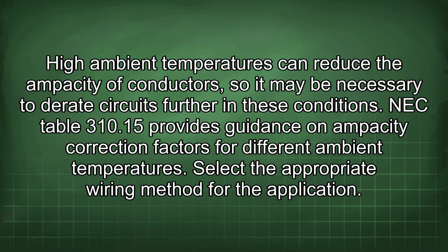High ambient temperatures can reduce the ampacity of conductors, so it may be necessary to derate circuits further in these conditions. NEC Table 310.15 provides guidance on ampacity correction factors for different ambient temperatures.